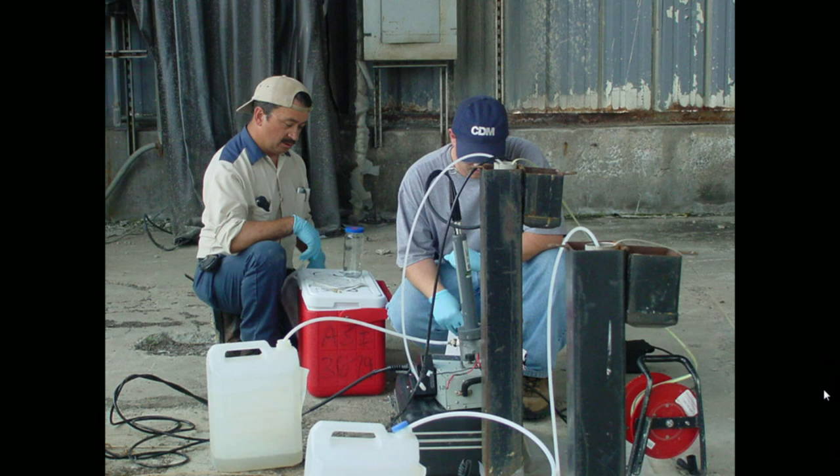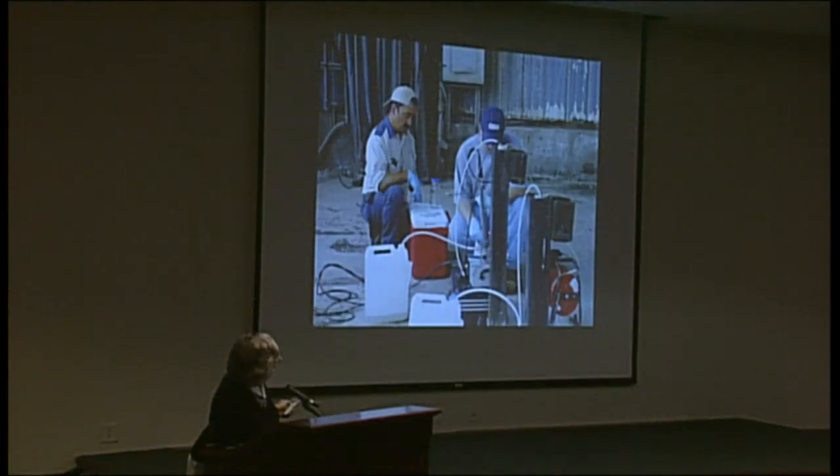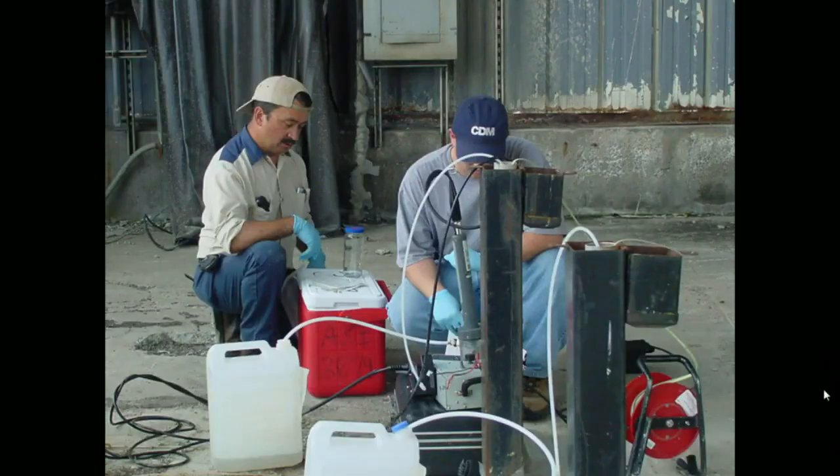Don't know if y'all, Robert, can see the laser pointer? So this is actually the flow-through cell. The water's coming out of the well, going into the bottom. It goes through the cell. This is the multi-parameter meter that measures different parameters, like DO, ORP, pH, conductivity. So it measures it as it's flowing through the cell, and then it flows out and is discharged into the container.